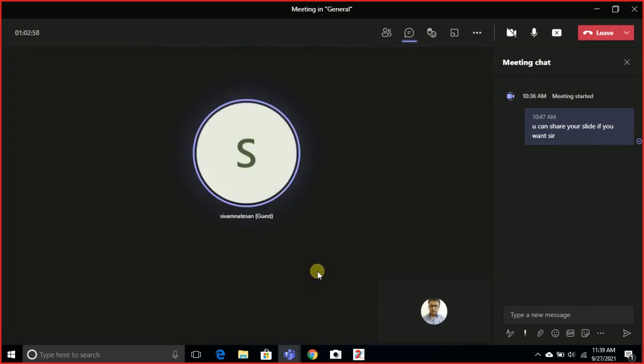Not 24 combinations. First, IO cells 1, 2, 3 and 4 will each have four pins, separate pins for input and separate pins for output. And the remaining IO cells 5, 6 and 7, the input and output pins are combined, so two pins for both input and output. The first four IO cells will have separate input and output pins, and 5, 6 and 7 will have the same input and output pins.